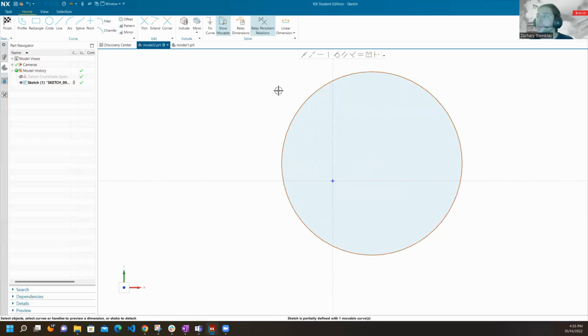Instead of rapid dimensions, to set some kind of geometry relations, the options are on the top over here. When you're in sketch mode, you're going to see them appear. We have options like making two lines collinear. We have options like making them coincident, making something horizontal, vertical, tangent, parallel, perpendicular, equal, symmetric, or make a midpoint aligned to something else.